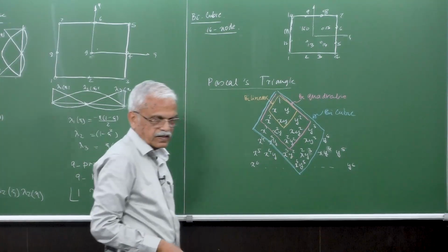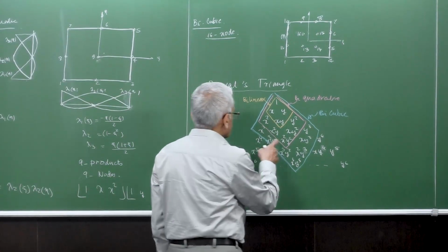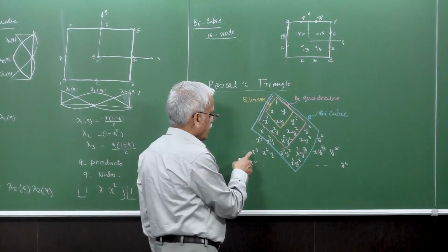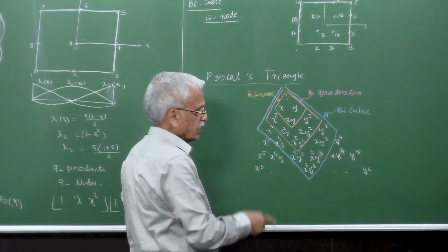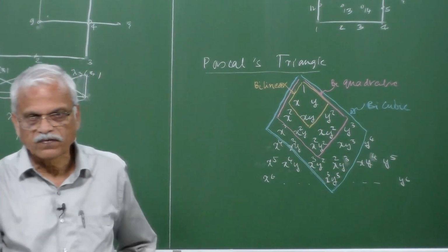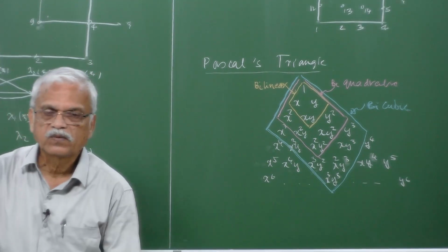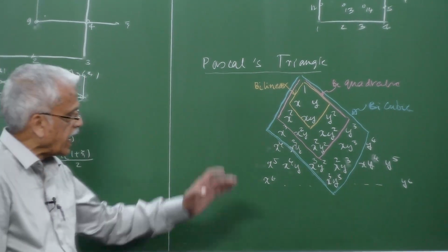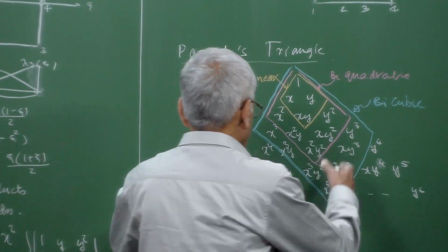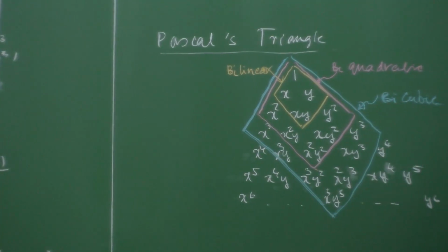So in this row of fifth degree polynomial, the approximation here is not complete in the fourth degree polynomial, or even fifth or even sixth. So these additional terms are there for the sake of constructing this element, but it's not going to help the element, or not to the point that it will improve the convergence rate.